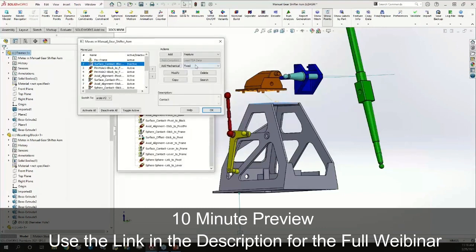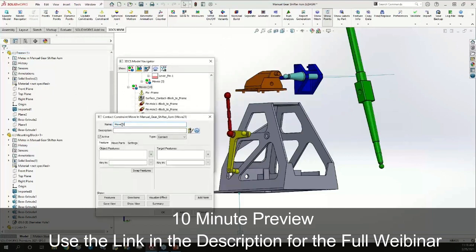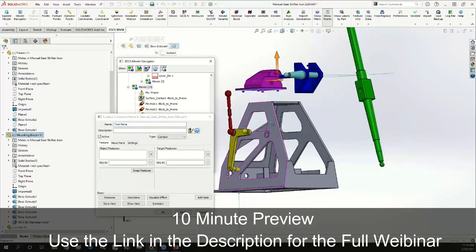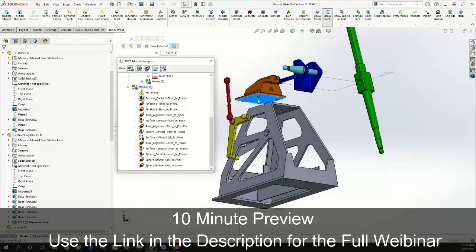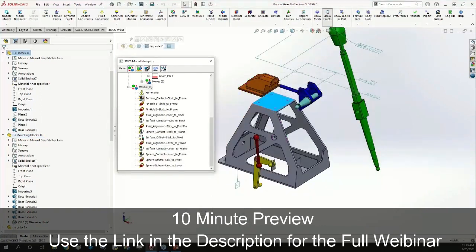is a contact constraint. Sometimes it's difficult for me to always remember what these different names are based on the icons, but that's a contact constraint. So I'll go ahead and select the contact constraint right here and click Add Mechanical. That'll open up a blank constraint dialog here. I'll just call this first move. And this is just going to be a planar contact between my block face here and then my frame face there. So I'll just select Add Feature on the object side, select the first feature, and then on the target side, there.